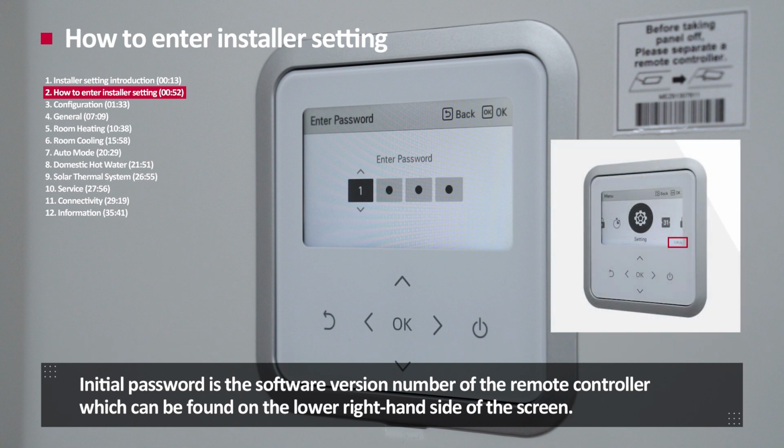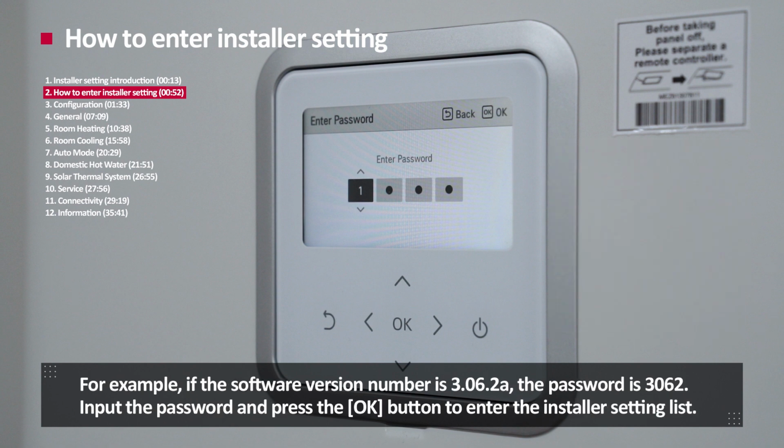Initial password is the software version number of the remote controller, which can be found on the lower right-hand side of the screen. For example, if the software version number is 3.06.2a, the password is 3062. Input the password and press the OK button to enter the installer setting list.